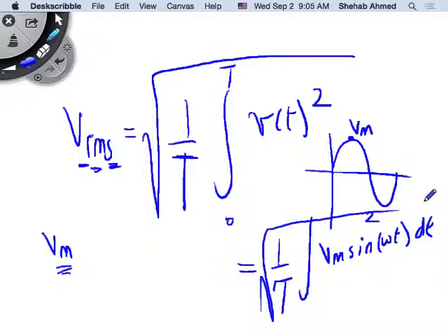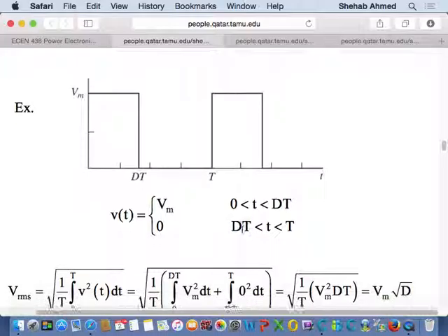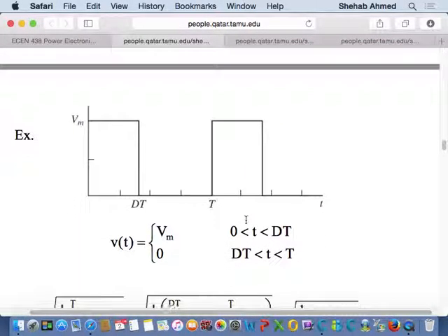You can do all of that. But what is the RMS value of a sinusoidal waveform? It's a number that you should have at the top of your head. Do you multiply by root 2? No, divide by root 2. So the RMS value of a sinusoidal waveform is Vmax over root 2. If you go through this, you will get the same, Vmax over square root of 2. And they prove it here, on the next slide.